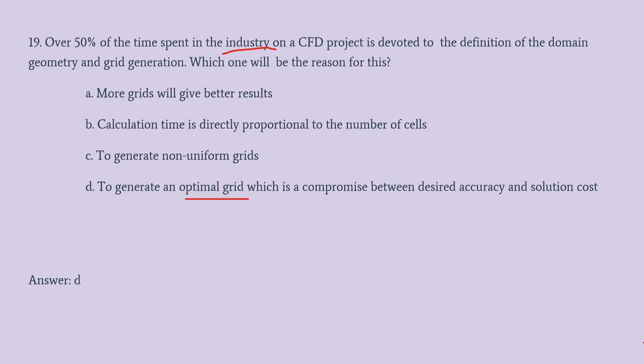If the mesh size is too large, the fish can slip through, and making the mesh size too small is actually irrelevant. It's an overkill. So our mesh size, that del x, del y, should be almost in terms with the variations of the property we are studying.